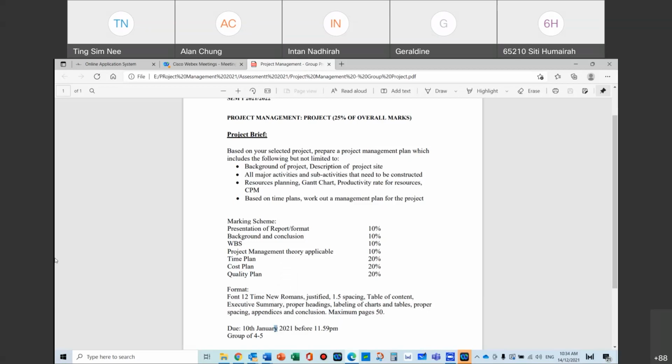Obviously, the machine may be in the booklet or in the catalog, saying that it can do so many cubic meters of soil a day, for example. But maybe you would need to factor it down a little bit, because it is run by a human being who can actually get sick or ill, or have moods. So you may have to factor whatever is in the catalog down a little bit, because it is run by a human being.